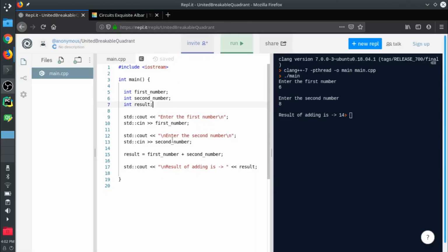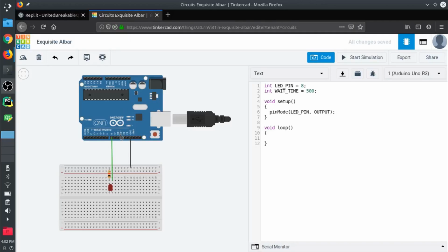Back in our regular C++ function, our output was the cout for the console, and our input was inputting from the console. In Arduino, we have all these different pins, and we can use them as either input or output. So in this case, I'm saying LED pin, which is what I'm going to be using here, is on 8. So if I move that wire somewhere else, let's say I moved it over to 10, I could just change this number here and all my code will still work. Now this loop is where the program actually runs. So this will get run over and over and over again.